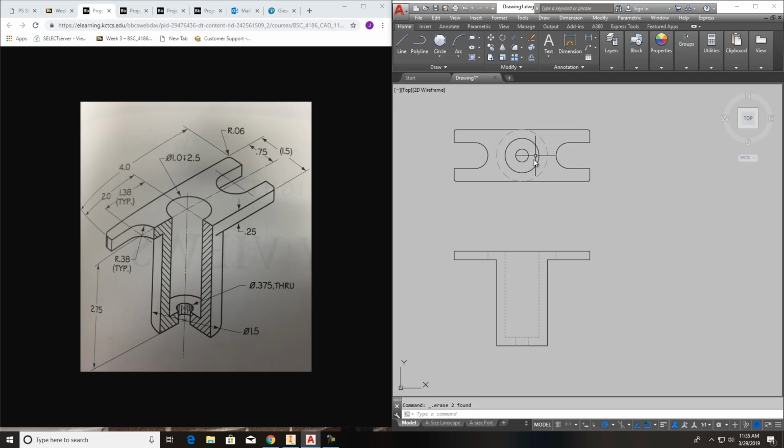So now you'll start dimensioning this thing, but it would look better if I'd done a section view. You can cut this thing completely through, or you can come through here and do the half section. Now, if you do a full section, it would look something like that. The cutting plane would go all the way across, okay?